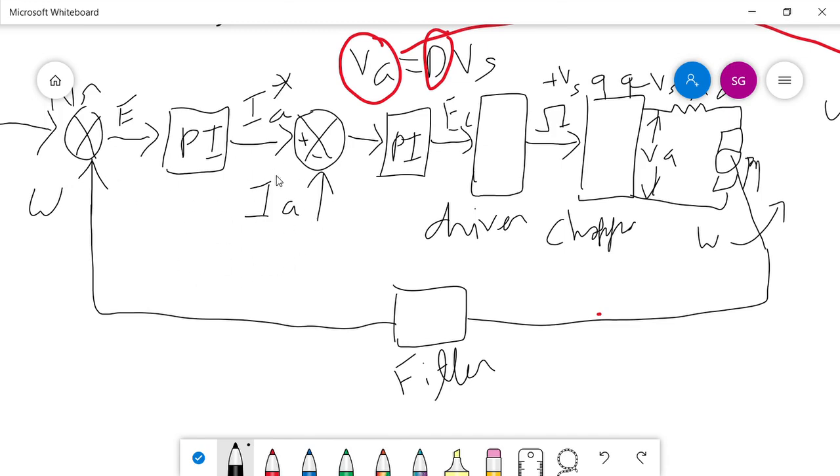And this IA, before discussing this IA, this complete is the outer speed control of your DC motor control logic. The speed error will be conditioned through a PI controller. This will generate an armature reference signal, which will be compared with the armature current of this DC motor.